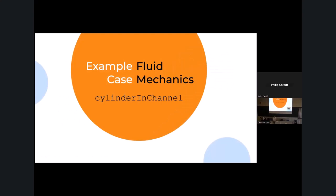Okay, I'll keep this part brief. You're not going to use solids4foam for doing a fluid analysis by default, but since we have to do FSI, you can actually do a pure fluid analysis in solids4foam as well if you wanted. So why would you do this? Well, if I port a new fluid solver, I might want to benchmark it and check it gives the same answer. There's only one tutorial called Cylinder and Channel.